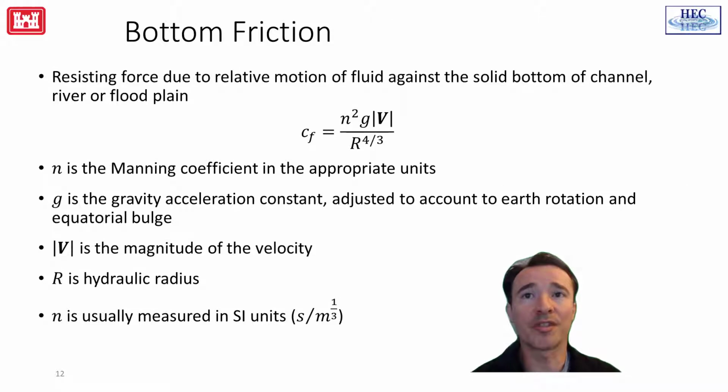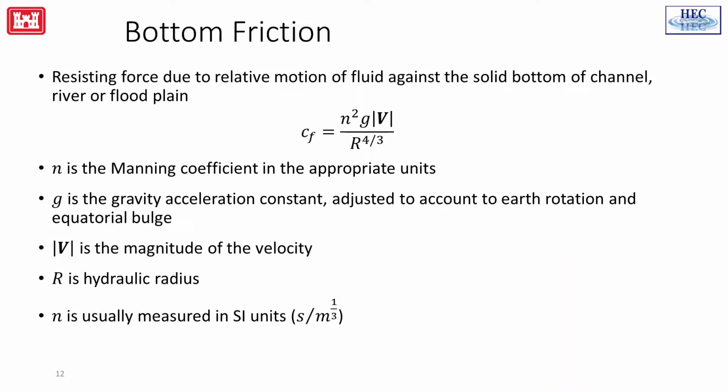Bottom friction is the resisting force due to the relative motion of the fluid against the bed. The nonlinear bottom friction coefficient in the momentum equation is computed as a function of the Manning's roughness coefficient, gravity, the velocity magnitude, and the hydraulic radius.